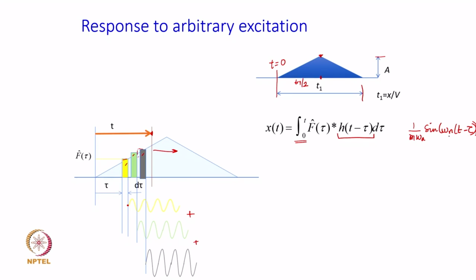Now, all of these parameters will be known, because if you know your system, the concrete tank has its own mass, and for the columns you can use basic solid mechanics to find the lateral stiffness. So, the values of k, m and obviously then omega n will all be known.